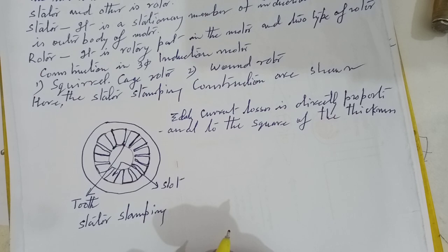As such, stator is laminated and the thickness of lamination is kept minimum possible to reduce the eddy current losses occurring in the stator.